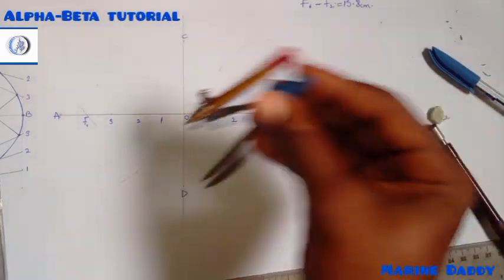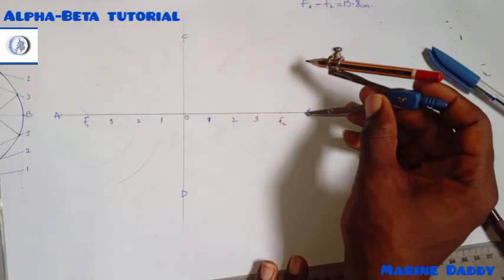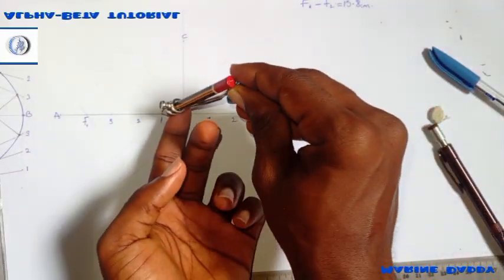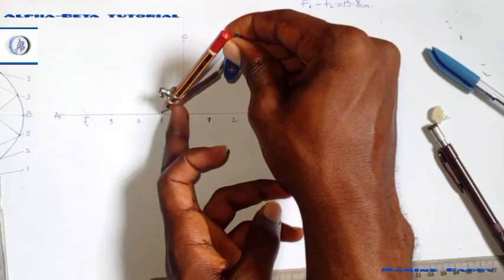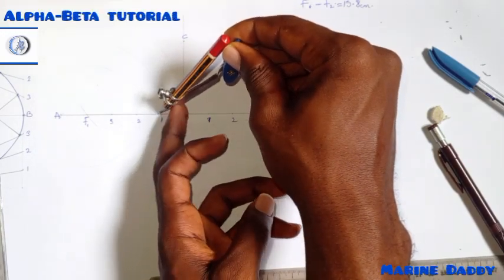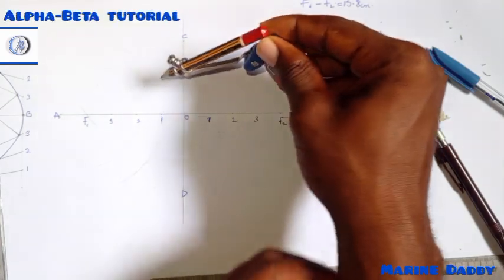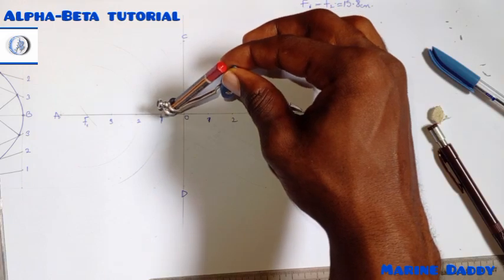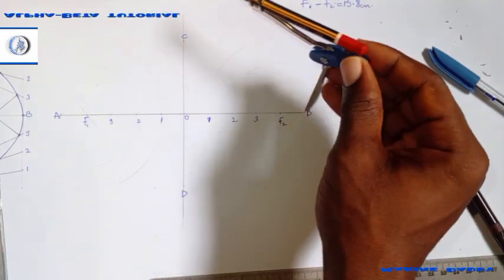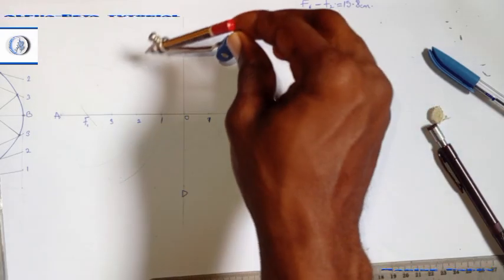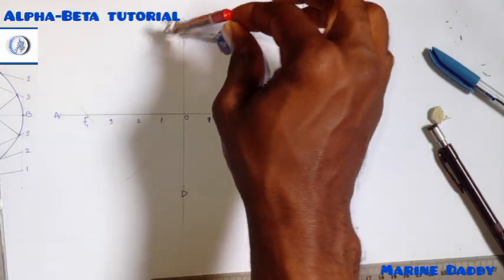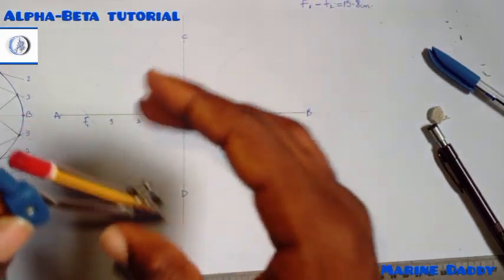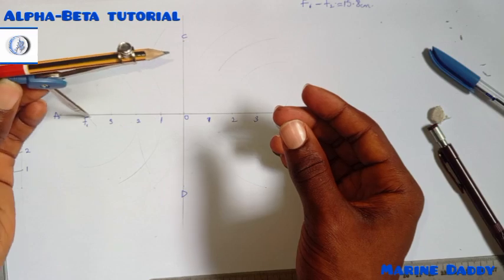Okay, now after doing this, open your compass at B or A, whichever one suits you. Move over to F1. To this one here. That's B to this side. B to 1 at the other part, or take it from A to B at the other side. Then intersect it at the initial one you got. Come to this side, repeat the same process from F.